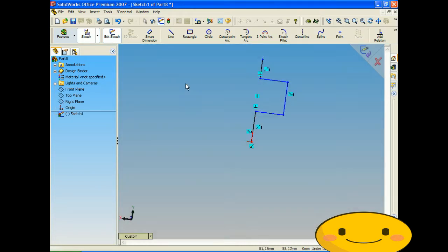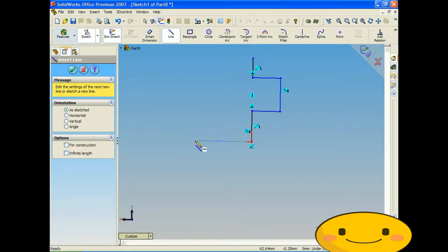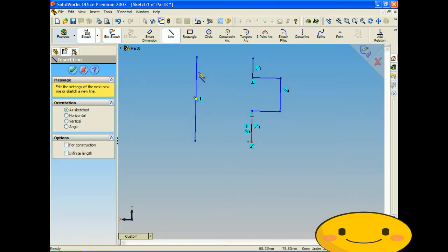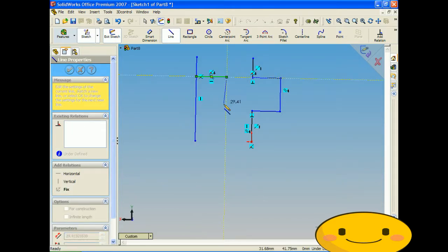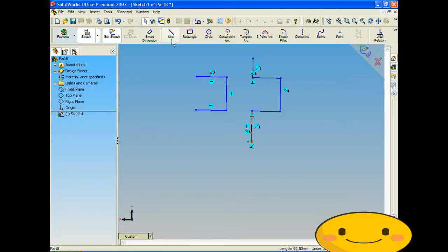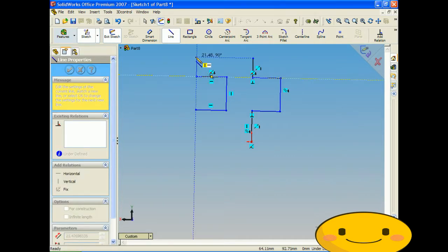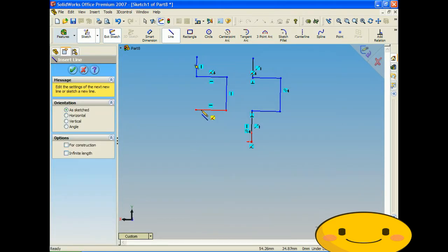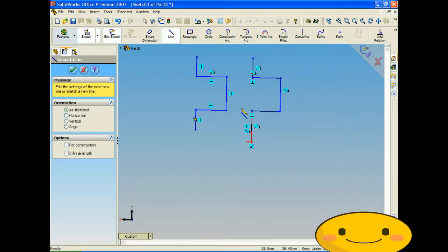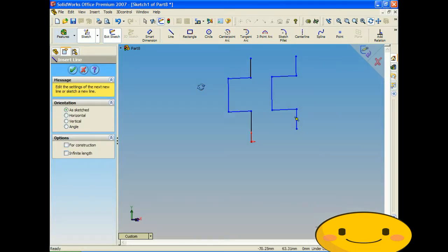So really, it saves you time because, let's see, say I had that line to begin with, and then I wanted to insert that jog. I'd have to go do this, go around like that. Then to get the bit in the middle gone, you'd have to delete that whole line there, go back individually, and add those endpoints. So it's a time saver if you want to add a jog such as that in the line.